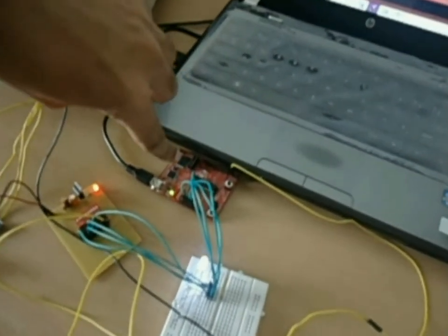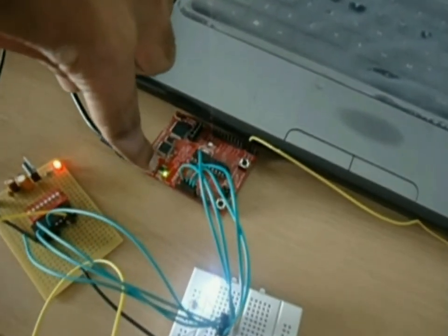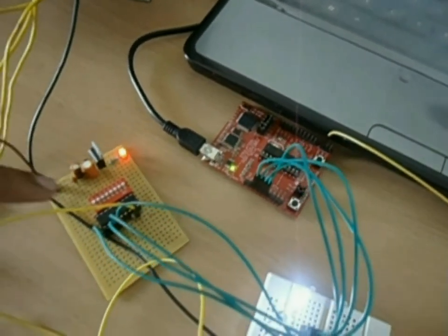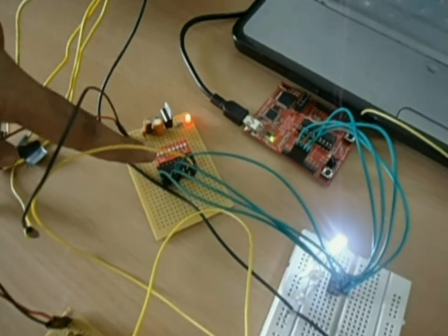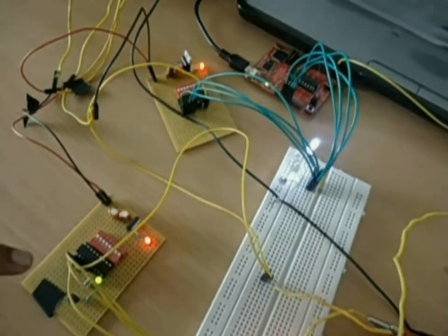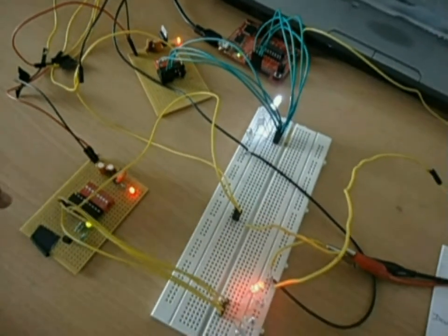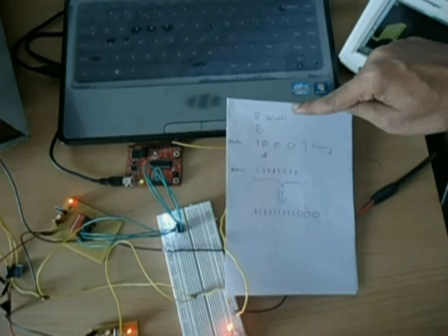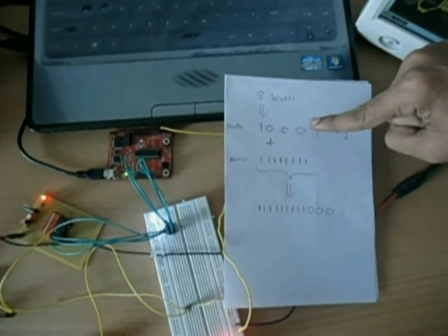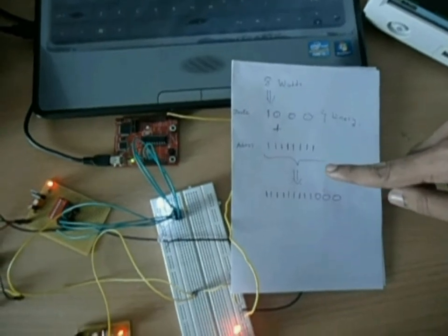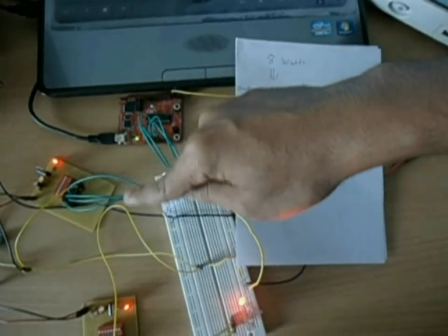The data from the household is converted to binary form by the microcontroller. The switches denote the address of the household. The address along with data are encoded by pulse width modulation. The decoder performs the inverse in the substation. For instance, if a house is consuming 8 watts, it is converted to binary form 1000 by the microcontroller and is appended to the address. This is encoded and sent to the substation.